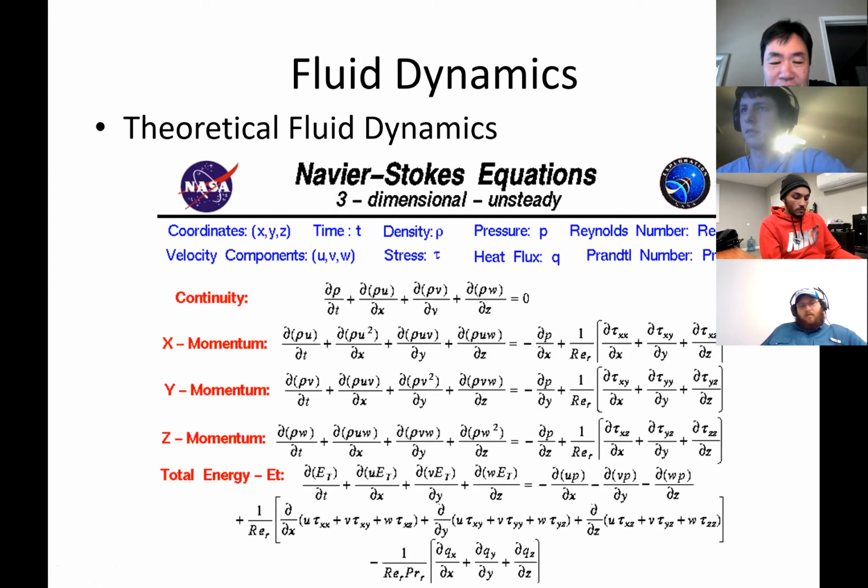When we talk about the flow equation, it's the Navier-Stokes equations. Unsolvable. It's nonlinear. These partial rho UV, those partial rho VV terms are the nonlinear terms. Any nonlinear term in a differential equation is probably a headache. It's non-solvable. So what's the strategy? What can we do? It's not solvable. So what do we do in this class?